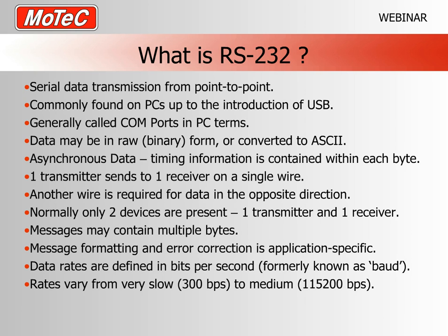So each of these asynchronous data bytes can be transmitted sequentially, and normally it may take multiple data bytes to form messages. So the messages are a formatted collection of bytes, typically to contain things like multiple values such as revs, throttle, and so forth. But normally a single byte on its own has no implicit meaning. It's usually used as a part of a message.